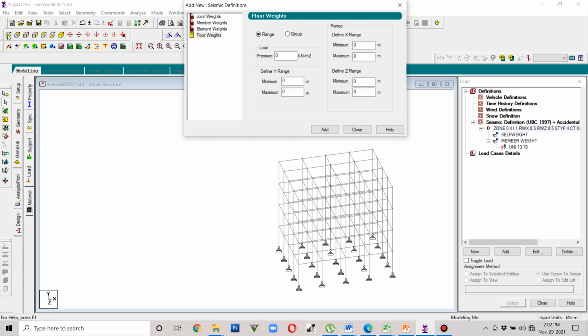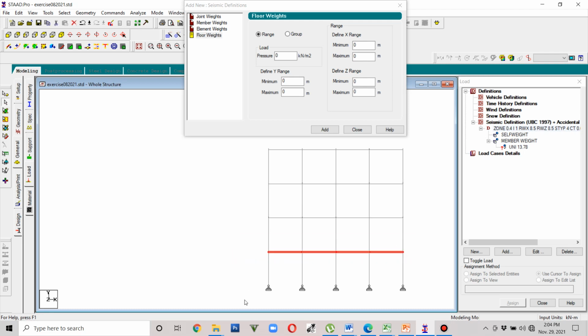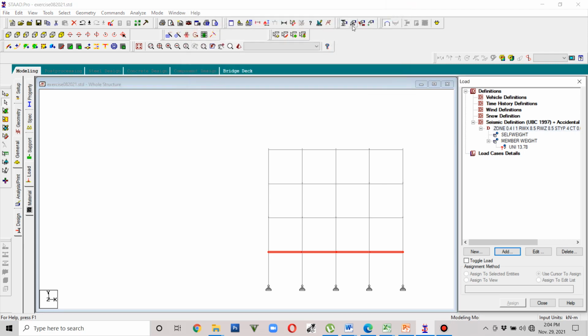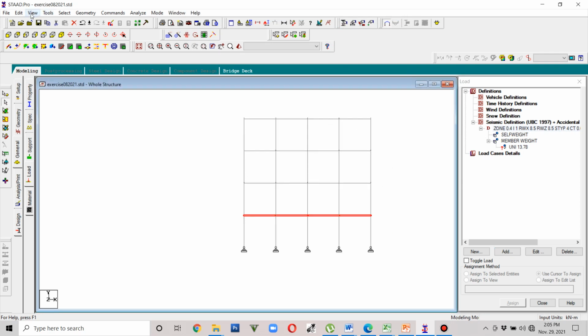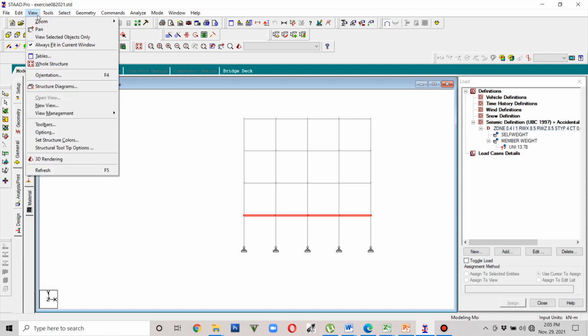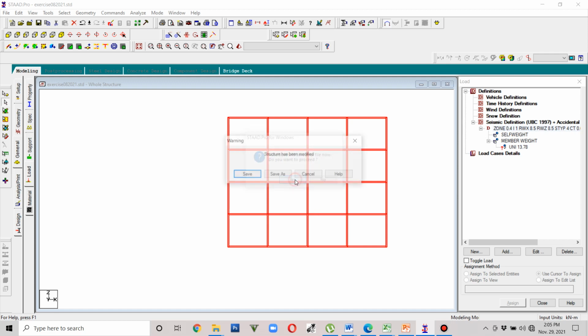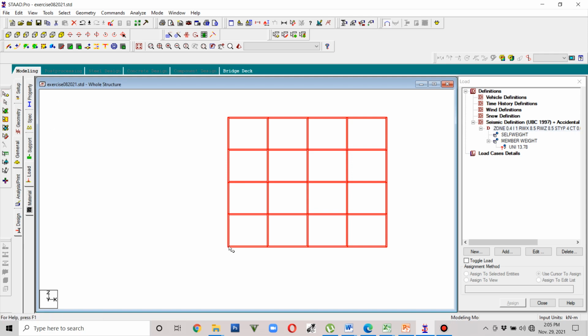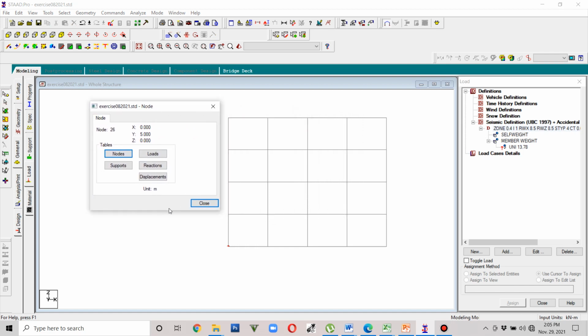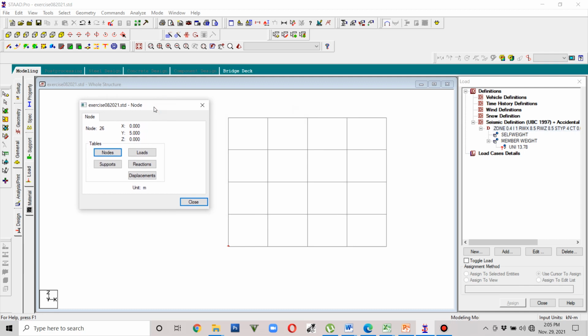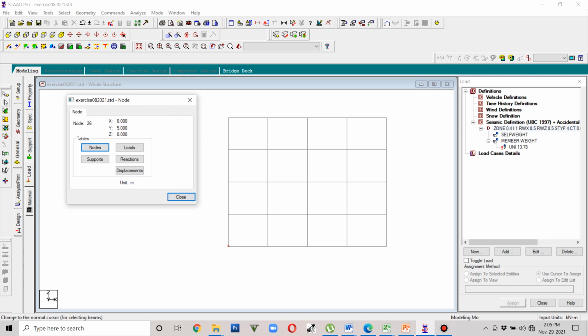Say we get first the section, so we get the coordinates. First things first, we isolate this. Say view selected objects only, and then we go to the ground floor. So we choose the select node cursor, to determine our range of values. So the first range, if we need to enclose, say I'm going to enclose this rectangle here.